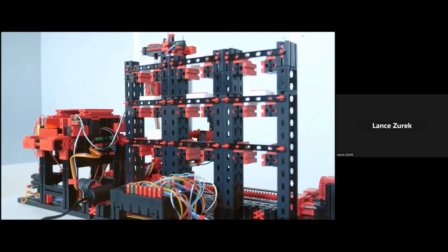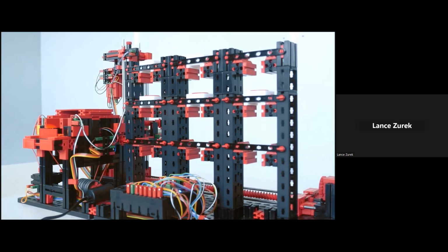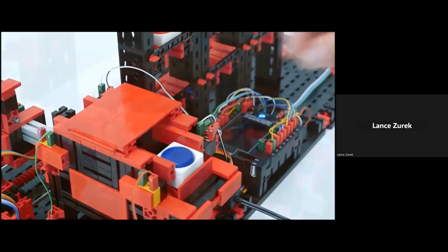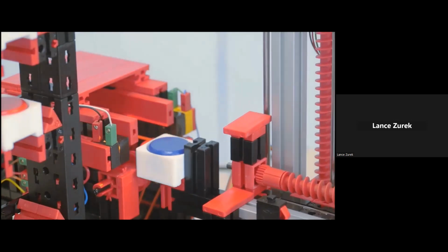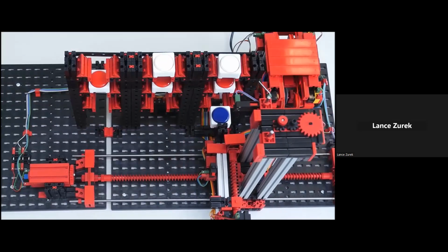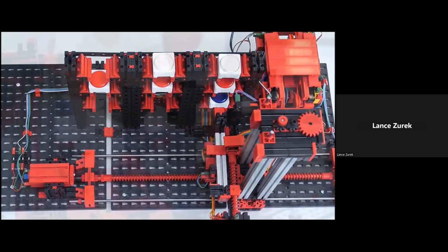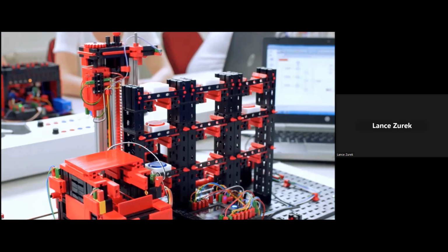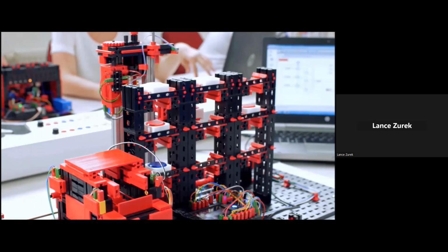The dimensions for the model are approximately 19 by 28.5 by 15 inches, and it has a weight of approximately 18 pounds. Once again, the 24-volt version has a relay board for motor polarity reversal and both a multi-pin connector, 34 pins with a grid of 2.54 millimeters, as well as additional PCB terminals with push-in connections for all inputs and outputs. Again, you will need to provide your own PLC and your own program.